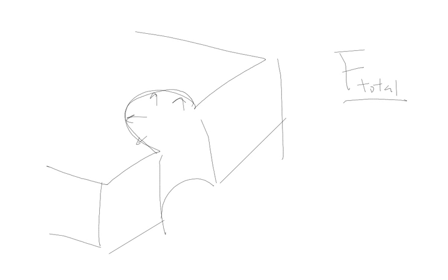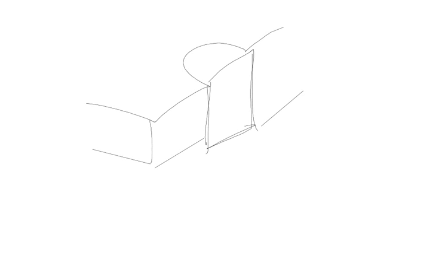And then you just take that total force divided by the area, that area of that semi-cylindrical surface, and that will give you your sigma, your stress. That's obviously going to be a lot of work, trying to integrate to find that total force. What actually ends up happening mathematically is there's no need for that integration. You will get the exact same result if you take the projected area. That's simply this area here.